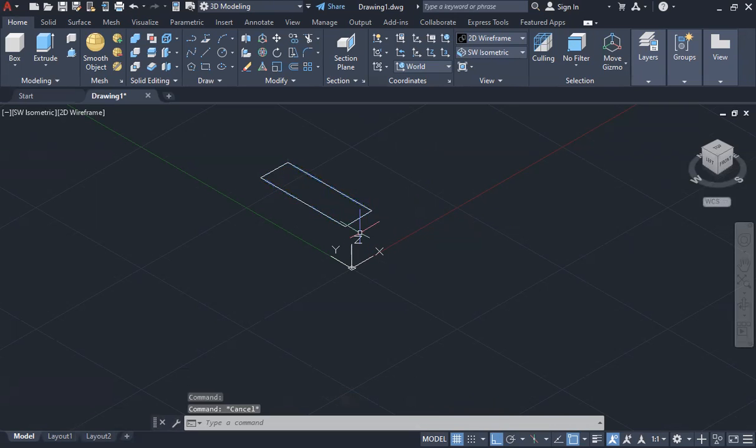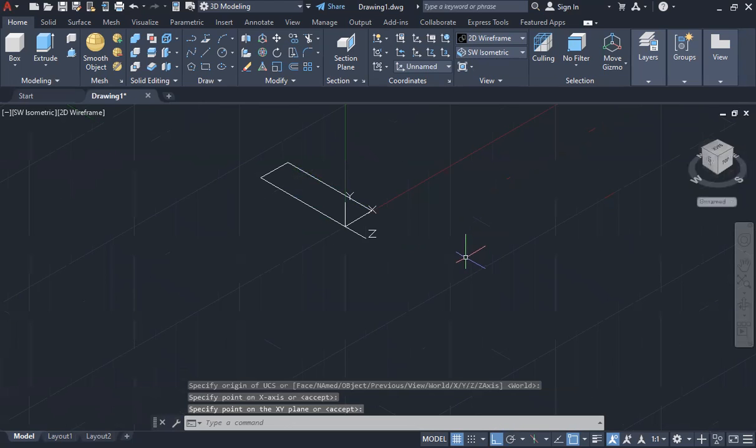Then we're going to move our UCS to that corner here. So UCS, set the origin to the corner, put X either this side or this side, and your Y to be vertical, either up or down. All right, everybody here? Sam, up there?